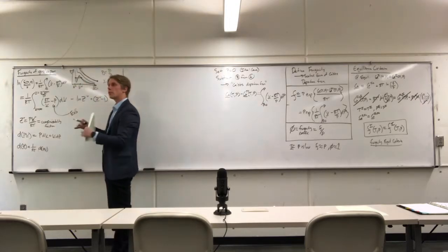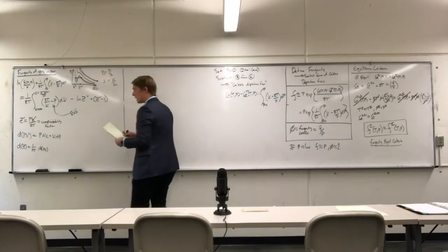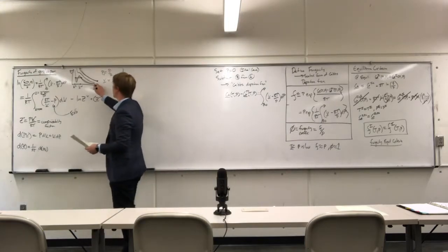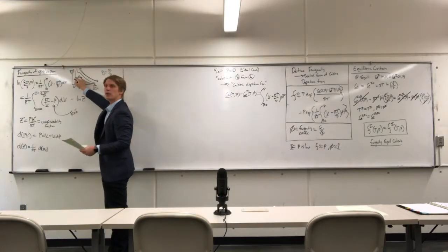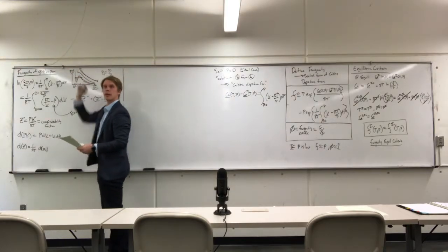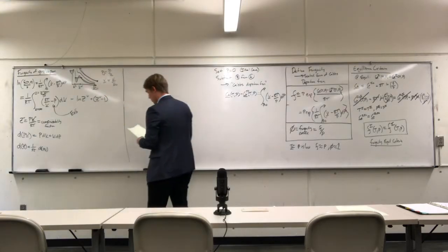So what we're going to do is break it up into different steps. Step one, we integrate from an ideal gas state to the saturated vapor. Step two, saturated vapor to saturated liquid. Step three, we're going to pressurize the liquid even further, and we're going to develop an expression for that.